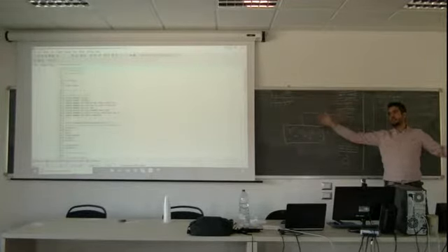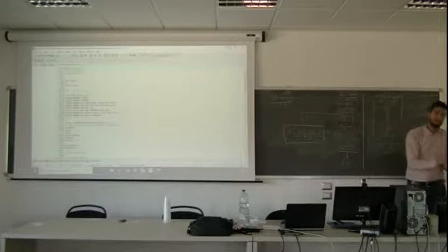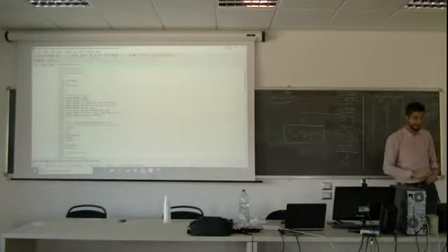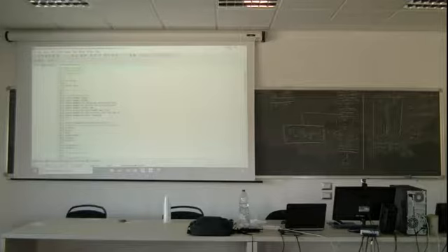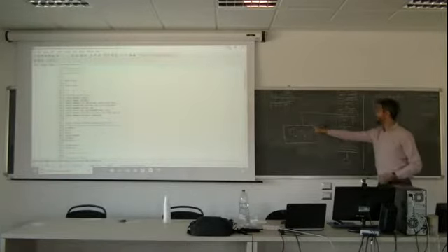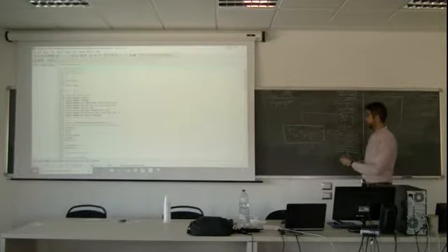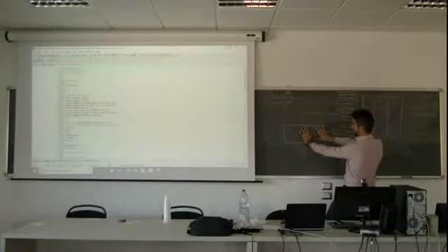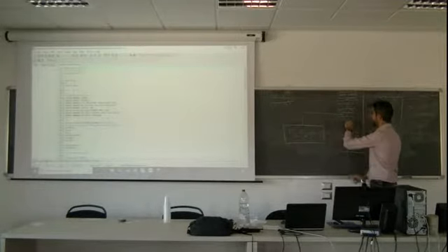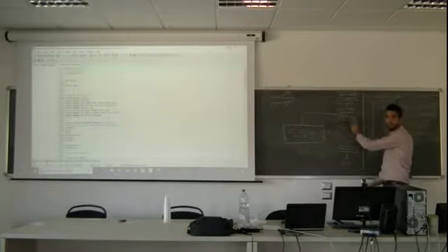One node is at 61, another node was at 58, they are not at 70. So my assumption was not correct. I need to adapt the assumption. Yesterday I said, okay, now my new assumption is the solution I got directly, right? And then I pass again. Yesterday I said, the new assumption was my solution, okay? And then I recharge and go to calculate again the temperatures.